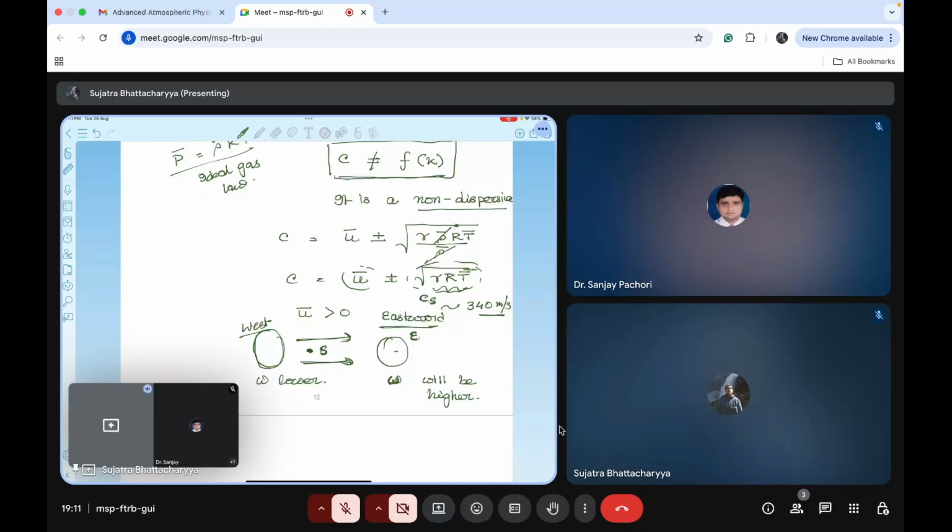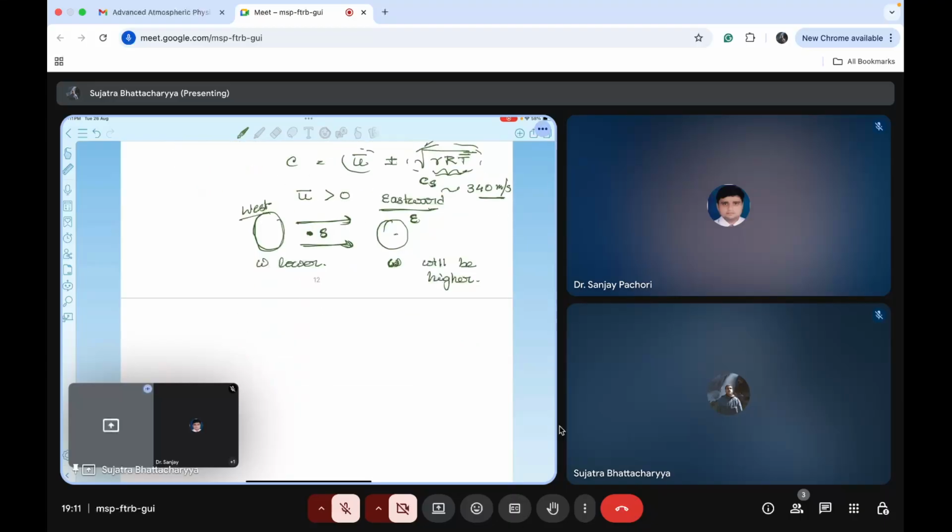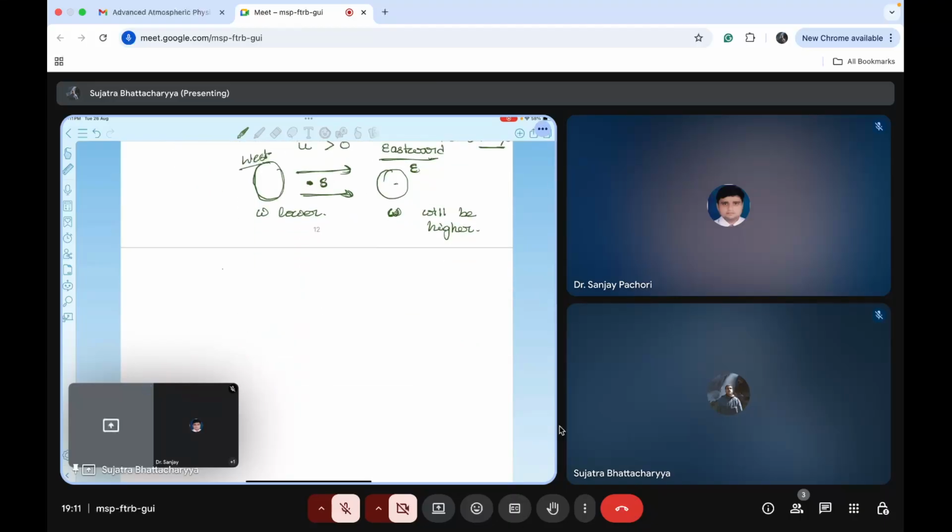The next thing after the acoustic wave is the second wave, which is the shallow water gravity wave. We will look into this. I will just quickly give you a hint of the deep water gravity wave and its group velocity and phase velocity. There is no derivation properly for that, but for shallow water, we have a derivation, and we will do that. I think in assignment 5, there is a question on some storm related thing.